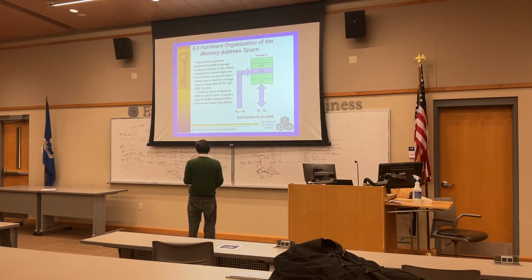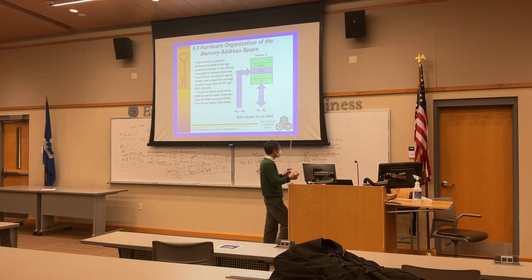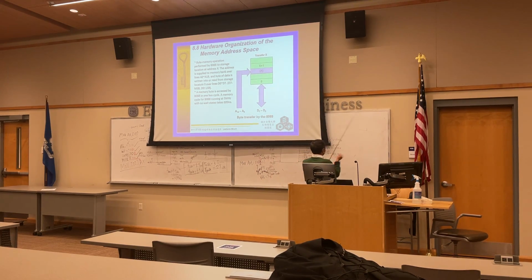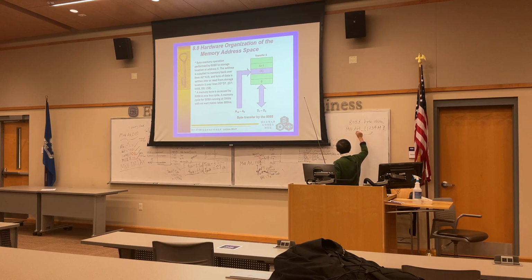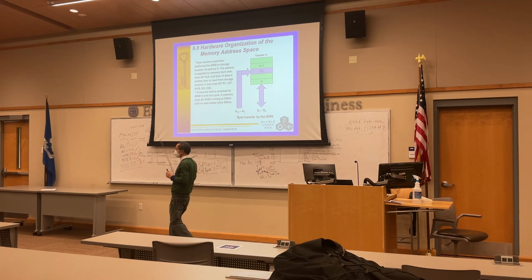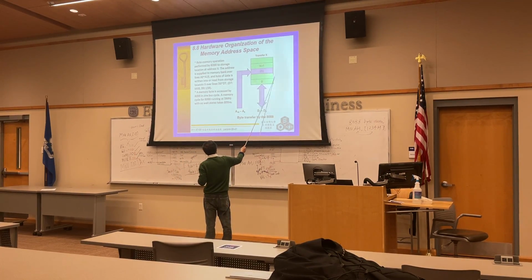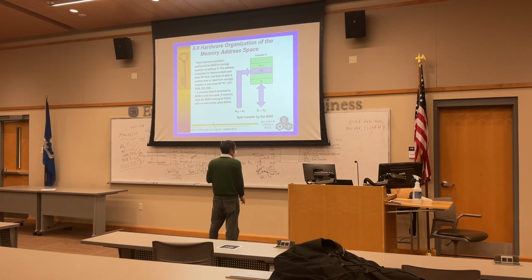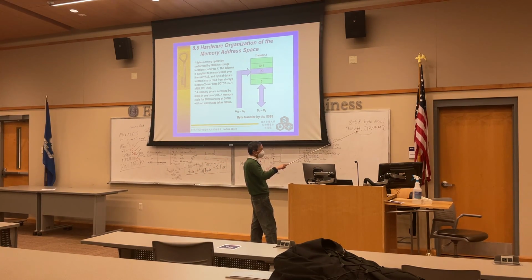First, the 8088 data byte transfer. For example, we are talking about MOV AH, [1234H]. 8088 makes it easy: the memory has only one bank. Alright, and then we are going to read the data from this memory location to the register.